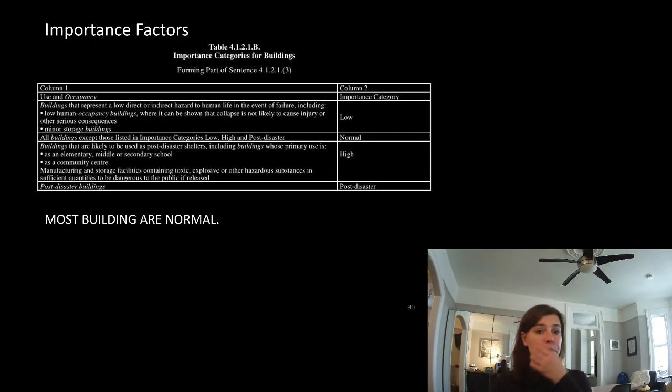They need to be prescribed in the building code, but then they need to have allowances made for location and type of building and the things happening around it. And so they build that in a few different ways. One of the other things they do with the climatic data is they say we're going to apply an importance factor. Basically, how important is your building to people? And this sounds funny because you would say, well, why wouldn't we just design everything to the maximum capacity? And the answer is money.